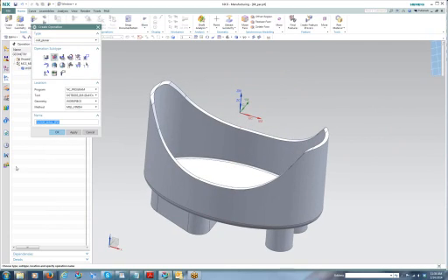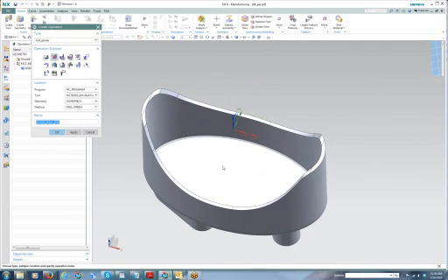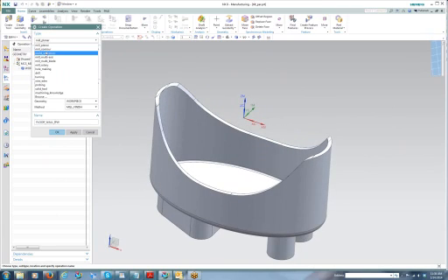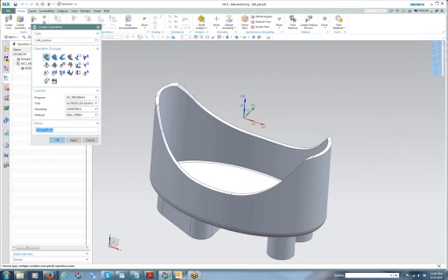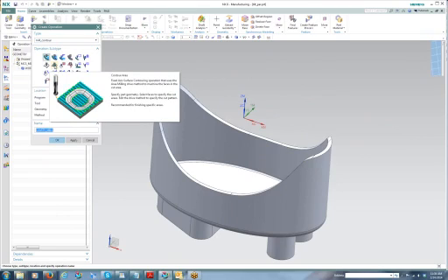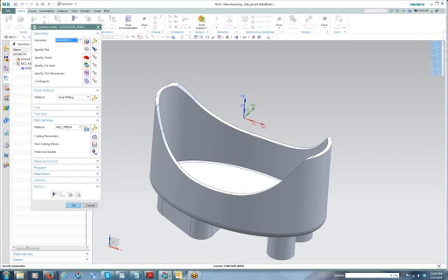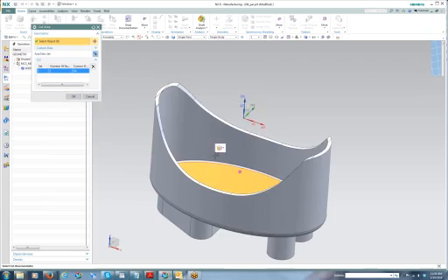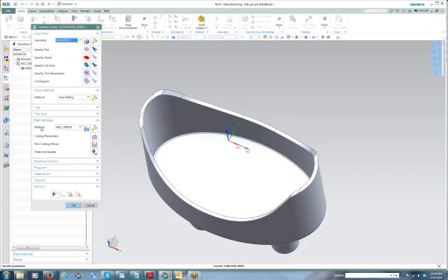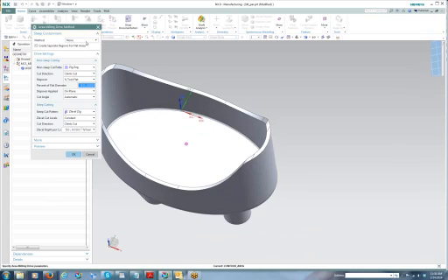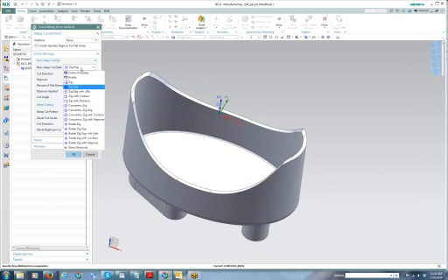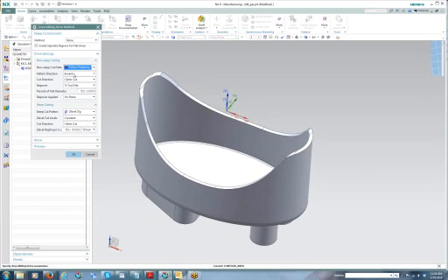Okay, so another use of the tilt tool axis is in a cavity situation like you see here. We'll start with a 3-axis toolpath and then convert it into a 5-axis toolpath using tilt tool axis. Here's the surface that I want to machine. And rather than zigzag, I'm going to choose to follow the periphery. And we'll cut outward. So we'll start at the middle and we'll cut outward.